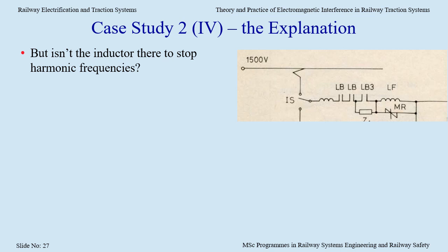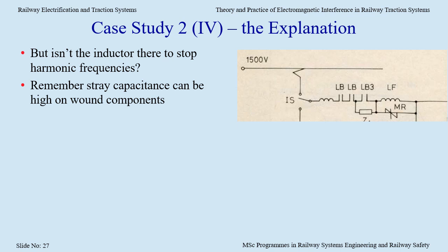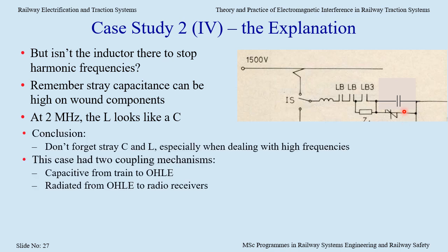But the inductor is there to stop harmonic frequencies getting onto the line, isn't it? Now remember that wound components can have significant stray capacitance between windings. So at 2 MHz, the inductance looks more like a capacitor with low impedance. Conclusion: don't forget stray capacitance and inductance, especially when dealing with high frequencies.